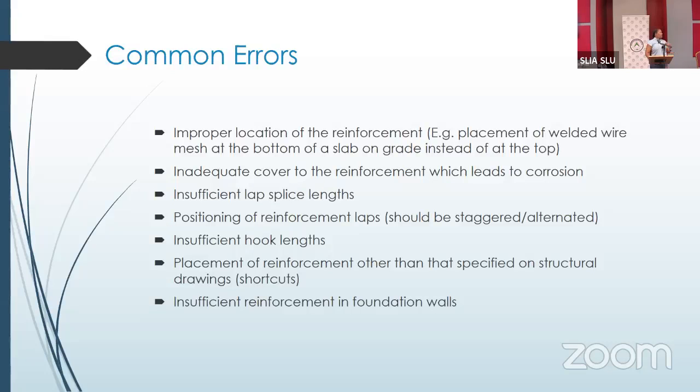Because there's no way that I am going to be using a building where I'm seeing my structural members have T10s in them. On top of which, the first floor slab was exposed, which means that it was exposed to water, all the elements. And you can see when you go on the ground floor, all of the water that was coming through the slab, which means that the steel inside of the slab has been compromised. So that in itself is going to cost tremendously just to retrofit it. A lot of things that we need to keep in mind.